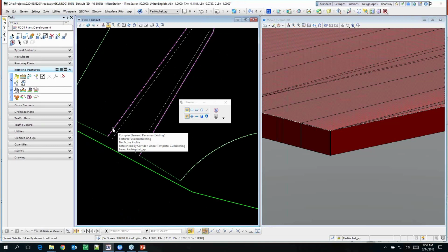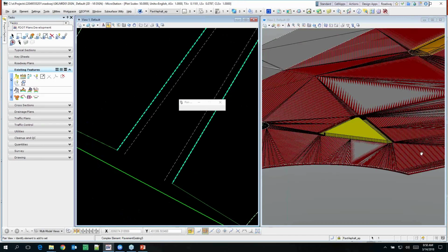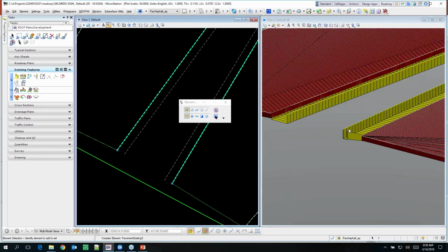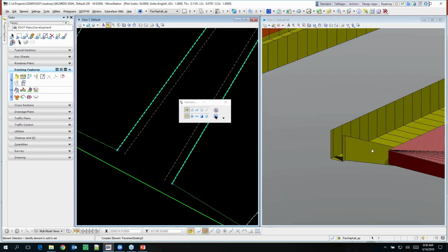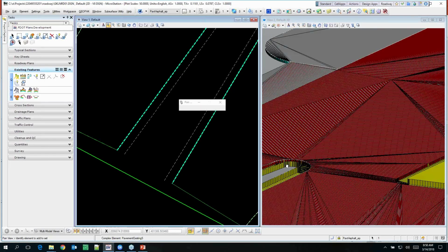The curb doesn't have a constant depth from the existing terrain, right? The front of a curb is usually about 7 inches deep, but the back of a curb is about 1 foot deep, according to our standards. We don't really know because what's in the field is in the field, so we approximate what we think it's going to be. You can't apply different depths to a shape.